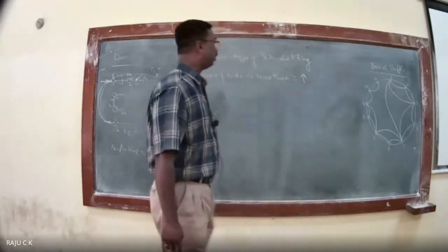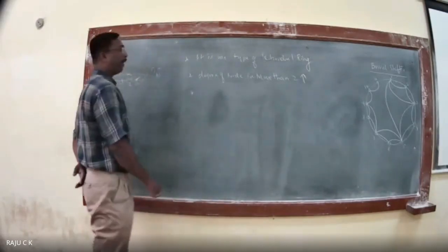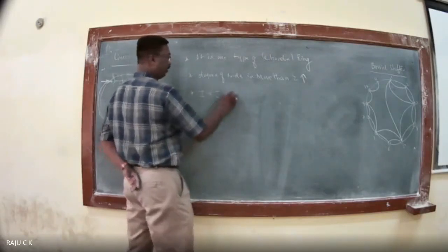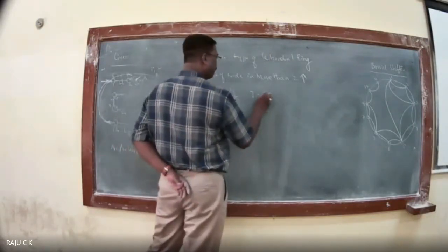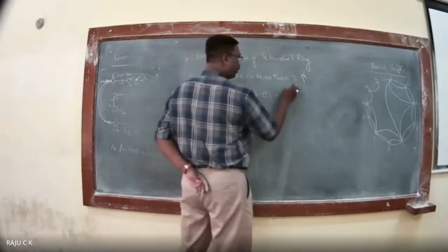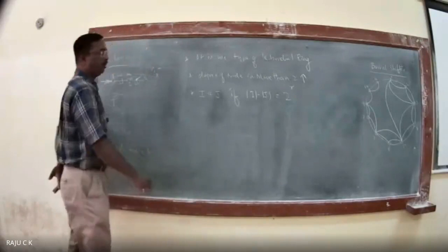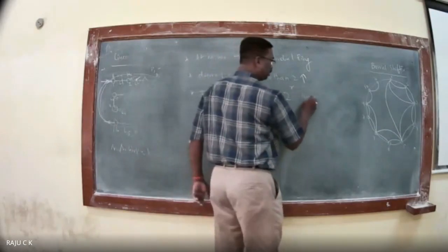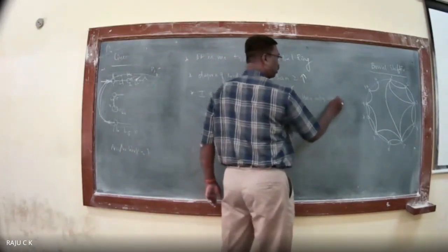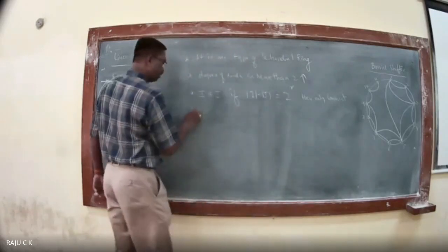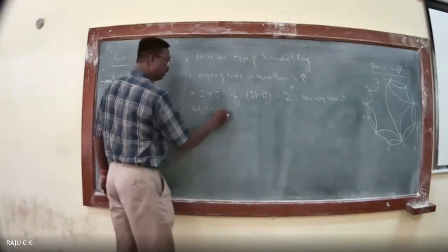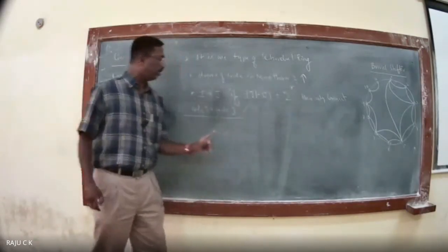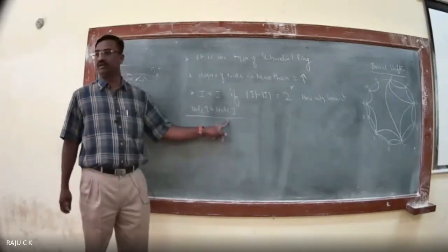You can see that. In the case of the barrel shifter, I want to connect node number I and node number J if the difference between I and J is equal to 2 to the power of R. Only then connect node I and node J.